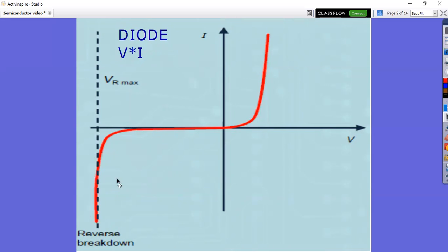And those Zener diodes are used in DC power supplies to clamp the DC voltage in reverse. So for example, if you want a 5-volt power supply, then you would probably choose maybe a 6.2 volt Zener diode to clamp the voltage and provide a stable power supply voltage no matter what the current drawn by the load.